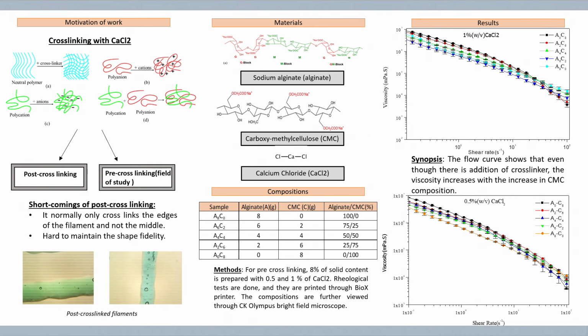So in this research particularly, we focus on the retention part of the 3D printing, ensuring the proper 3D shape fidelity of the scaffolds by cross-linking them. We can either pre-cross-link the scaffolds or post-cross-link them to change them from gel to more firm consistency. Some of our past research and findings from post-cross-linking suggested poor shape fidelity and motivated us to try pre-cross-linking the hydrogels with calcium chloride.